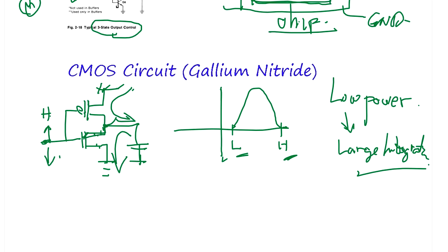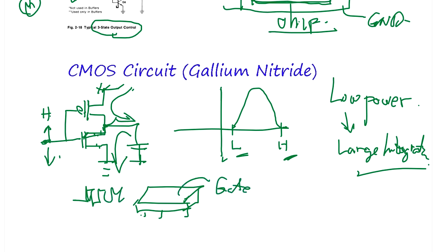Okay, so with a CMOS chip like a CPU, what happens is it consumes a lot of power when the clock speed is high and many gates are switching. When it's not doing anything, the power goes low. So the total power going into a CMOS chip depends on what the chip is doing. But it averages out because usually it's a large concentration. So for large LSI or VLSI, very large chips, CMOS is the way to go to mostly reduce power.